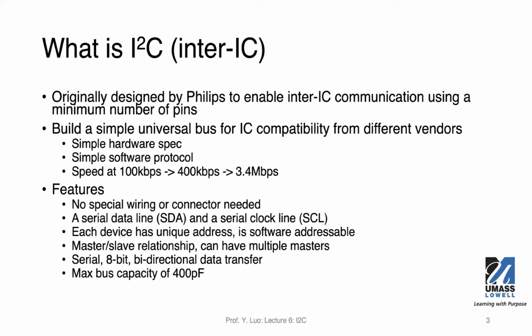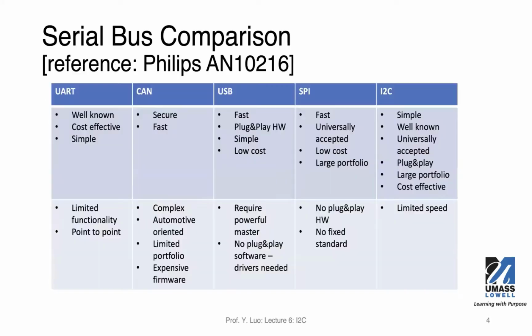You can do bidirectional data transfer. Let's say you have a master and a slave. You can write from the master to the slave, or read from the slave device to the master device using the same 2 wires. And the max bus capacitance is 400 picofarads.